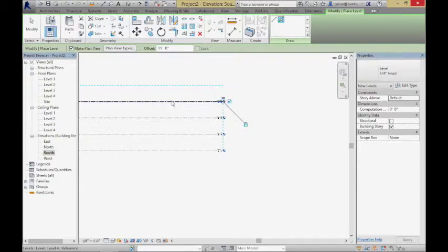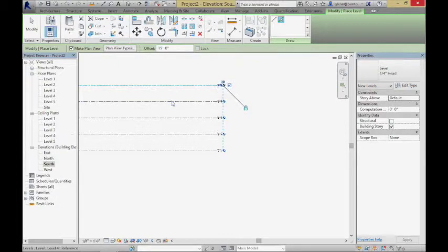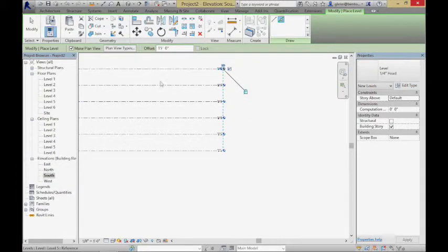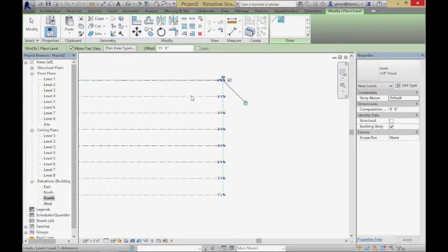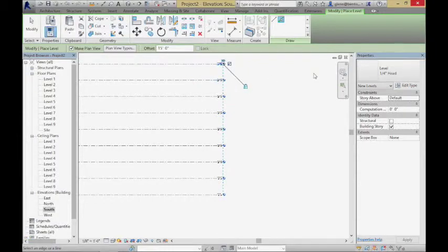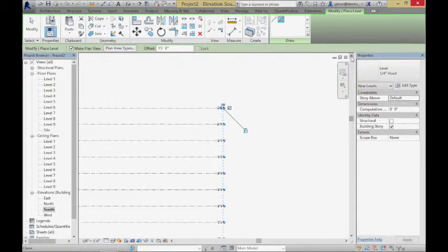That's just kind of a quickie way. Again, you don't have to be offsetting and doing it that way. You can be drawing them. That's okay. Just whatever works for you. I just tend to like offsetting because it's a really quick way of generating a bunch of them. Okay, so I'm just going to give myself some levels. Again, I may not use all these levels. I'm just giving myself some room so that as I create some different shapes, I'm going to allow that it could possibly be 10 stories.